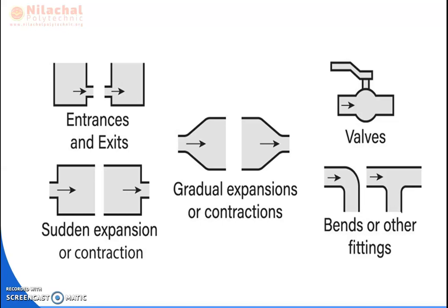Due to the decrease in diameter, the velocity increases, kinetic energy increases, and a pressure energy drop takes place. While using any valve, there may be leakage at the valve point, that is a loss of air. During bending of the pipes, while the pipe is running in a horizontal path and you suddenly bend it, a force is applied due to the bending, and due to that force some amount of pressure energy drop takes place. The velocity also decreases. Hence, that is known as minor loss in the pipe.